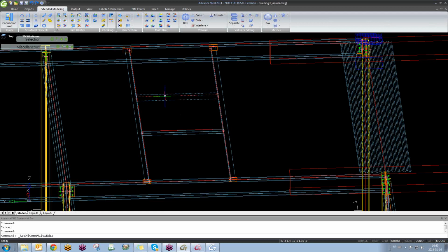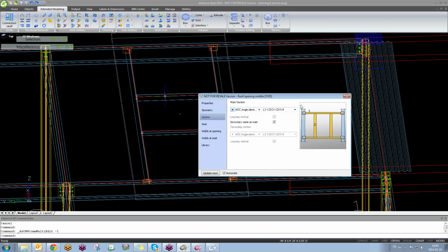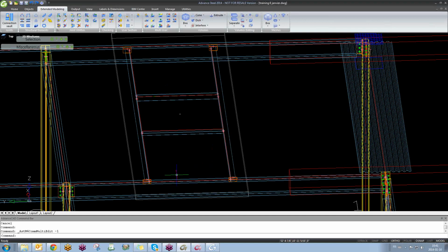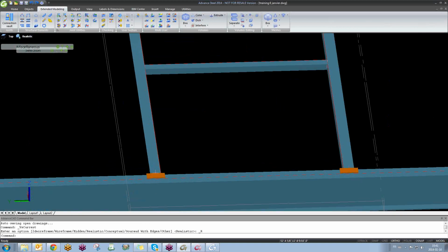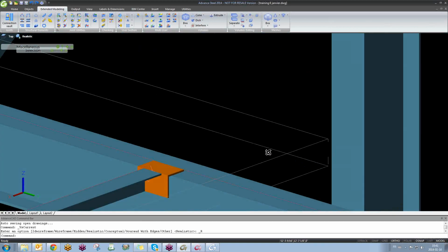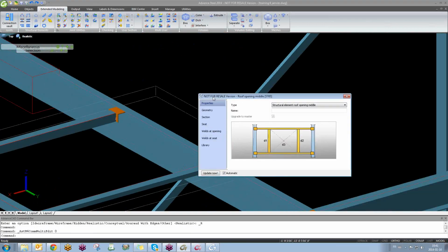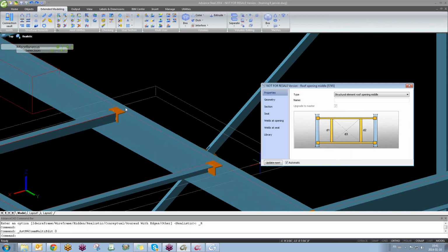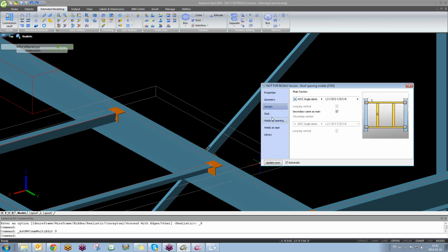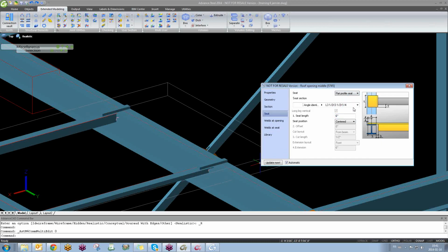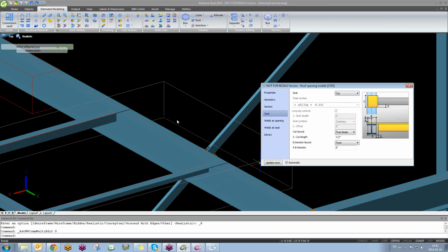Right. Just go to Advanced Drawing Properties. If you have geometry, sections, browse for your, instead of angles, put something else. Let's say I just wanted to notch out the angle to sit on top of the joist. Are you talking about here? It's already on top of them, I think. But what if I didn't want that connection angle, and I just wanted to notch out the frame angle, just to be welded directly? Weld as opening. Seat angle, cut, flat profile. Yeah, I see it there. Cut. Do you want it cut here?